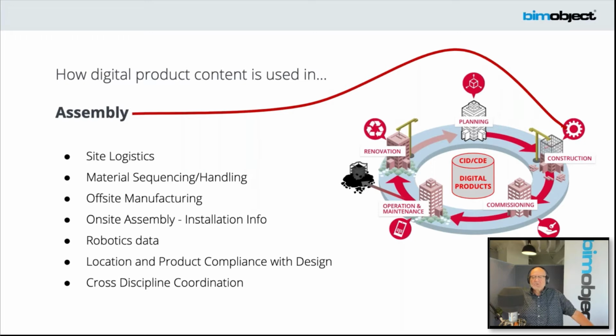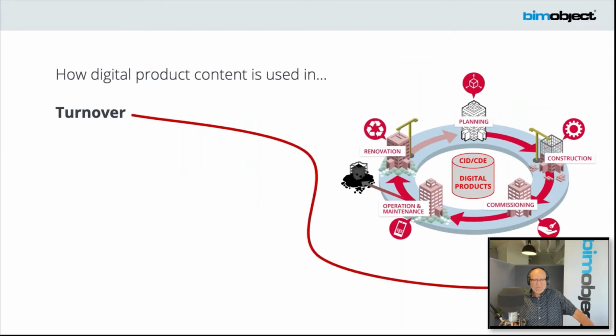Cross-discipline coordination. This is another huge one. The various trades sequencing. This kind of ties in with the sequencing. What order are the various mechanical systems going in? Because certain ones have to supersede others, or it may be much more favorable from an installation perspective to hang all the air duct prior to the fire sprinkler going in. I know some of this is figured out manually now, but a lot of this, even segments of systems being put in with other ones being put in later, because they're able to coordinate this installation across multiple disciplines. So we've got our building pretty much completed.